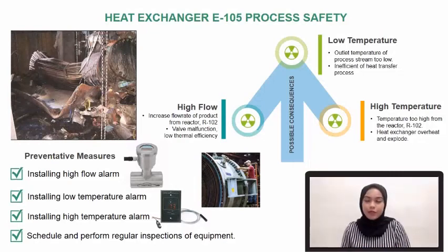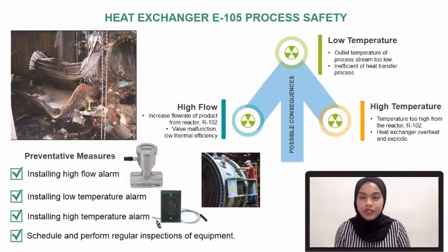Preventative measures that can be taken into consideration are to install a high flow alarm, a low temperature alarm, and a high temperature alarm. Scheduling and performing regular inspection is very important to maintain the process safety of the equipment. Okay, that's all for the design of the heat exchanger.